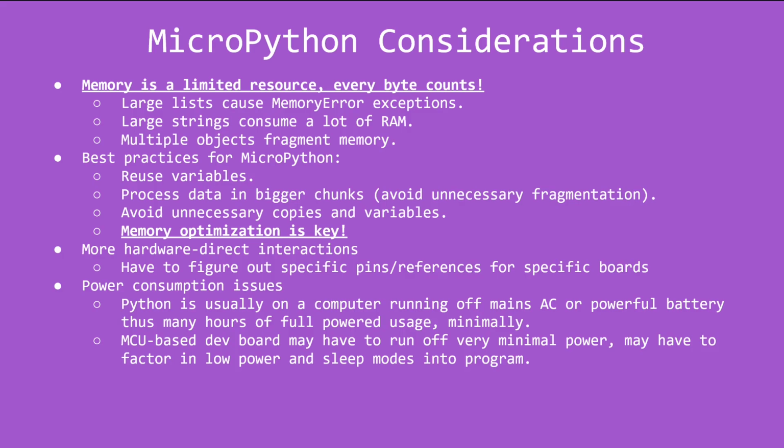There are also more direct hardware interactions. You're going to have to figure out specific pin references for specific boards. Do not assume that a MicroPython program is going to work flawlessly from one board to another. You can also run into power consumption issues here.